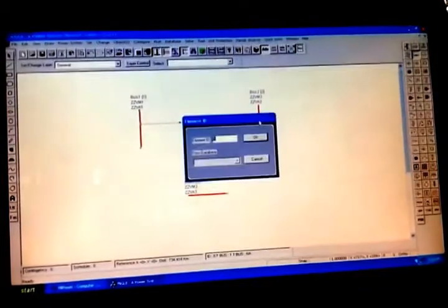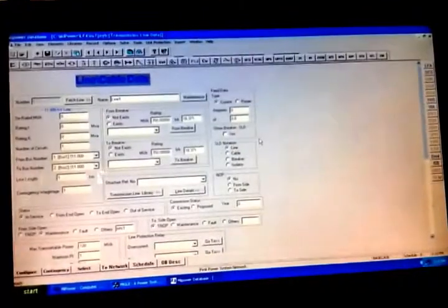Now select the transmission line. So we need to draw the transmission line between two buses, which should be a straight line. So select the orthogonal mode. Now click in between the two buses where you want to connect the transmission line. Double click on it, from bus, then to bus, give OK.